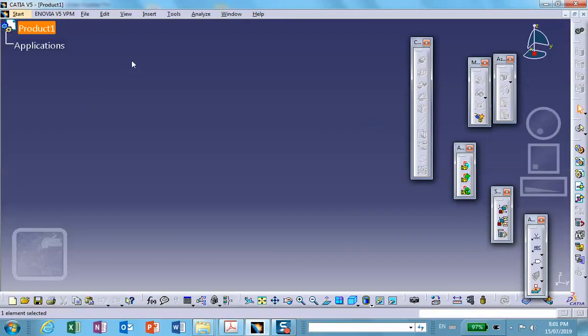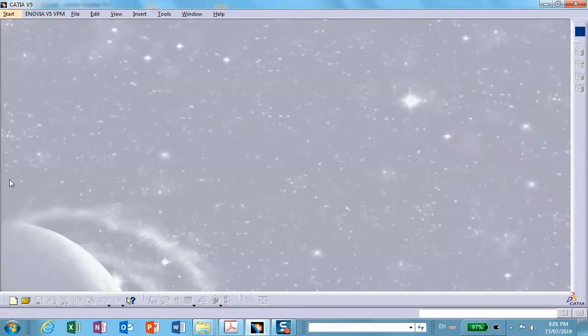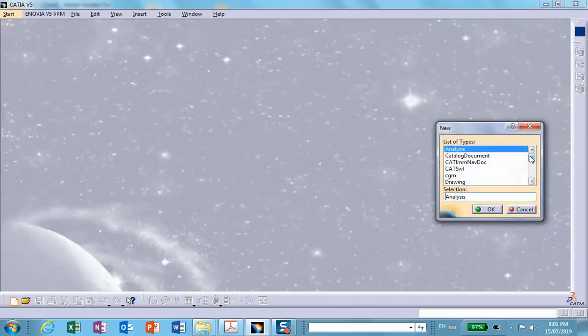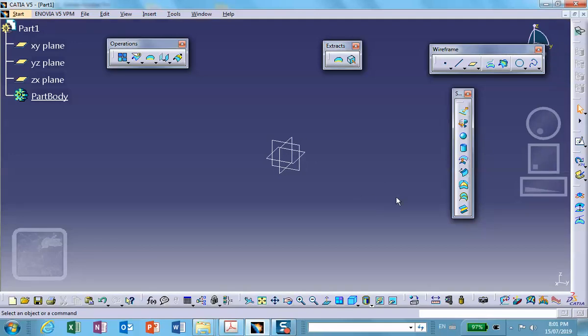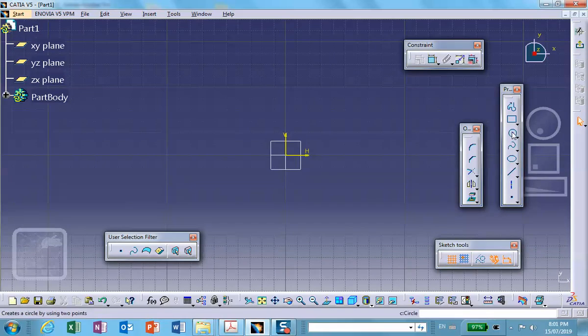All right. So let's start with a part file, because I already told you that I was not going to do that with an assembly. Okay, so let's start here. On a convenient plane, on this horizontal plane, I will sketch a circle. This is the circle which is representing that solid.